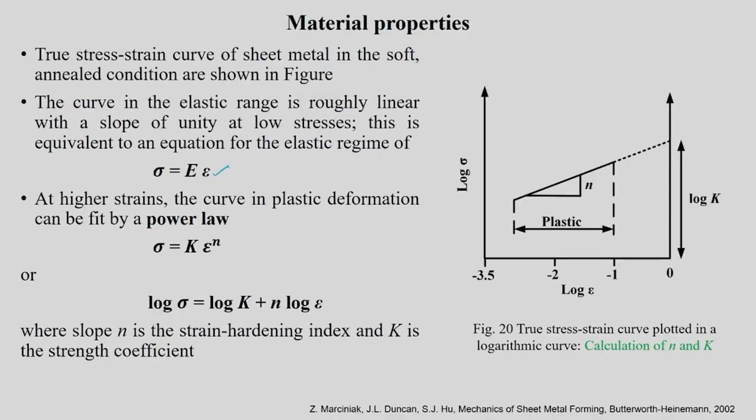In the elastic part of deformation, we know Hooke's law, sigma is equal to E into epsilon, which is going to be useful predominantly to describe the stress strain relationship, where E is your Young's modulus, which you calculated before. But beyond that, this equation has to be modified, and there are several equations of that type. We will see a little later what they are. One important one is the power law, sigma is equal to k epsilon power n. This is like a power law, y is equal to a x power b type.